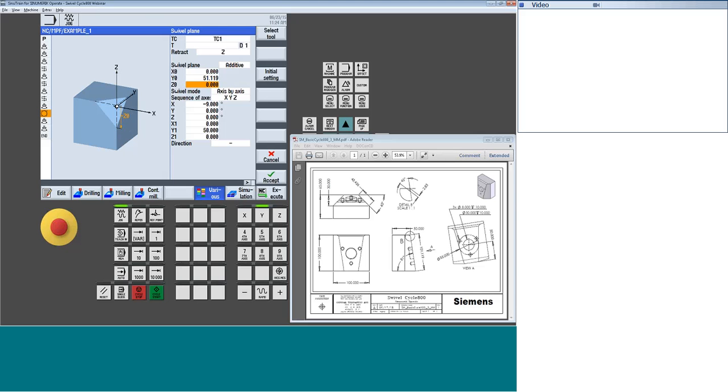Once I get there, I'm doing a rotation. So now, what am I rotating about? I'm rotating about my X, right? And I'm rotating about my X an additional negative 45. So that will get me to that orientation plane. If for some reason I didn't want to position this in X along that, maybe I wanted it in Y, you could certainly do like a negative 90-degree rotation that spins the whole work coordinate system. So now I'll be positioning in Y, even though you would think that it would be X motion.